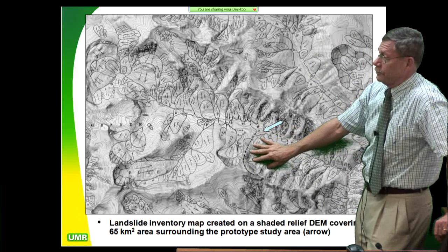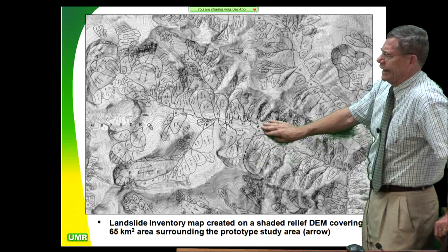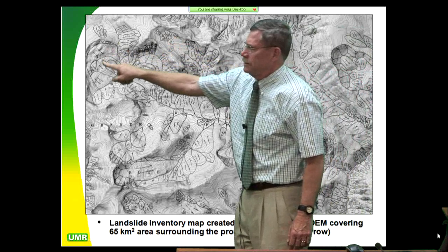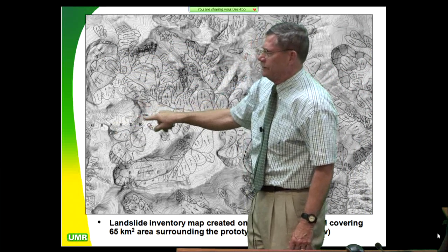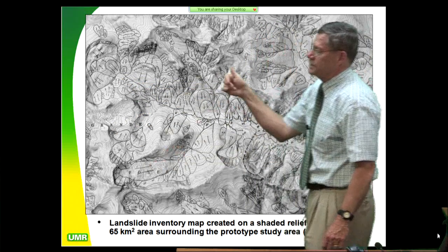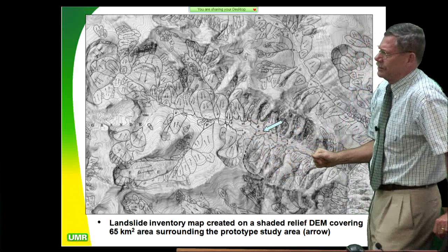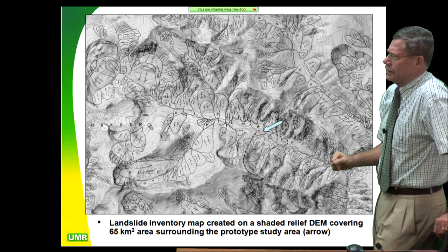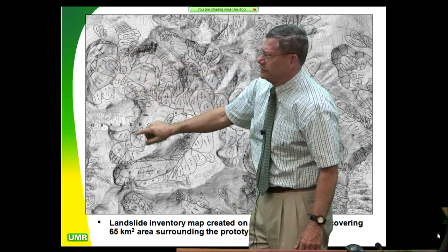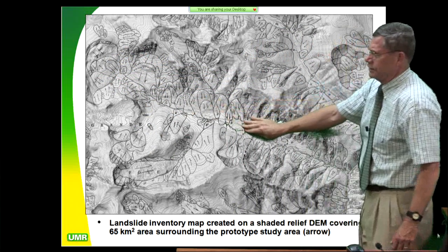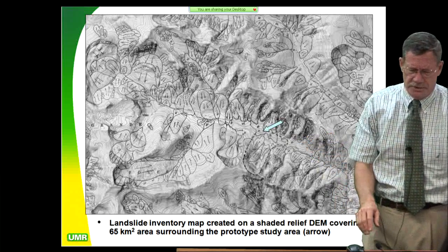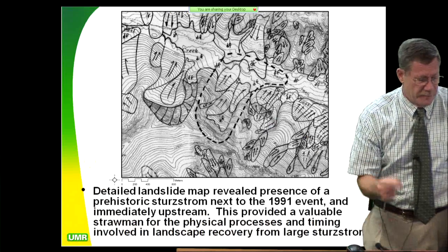This is the topography prior to the failure we were looking at. And there's only about 4.5 square miles of watershed above that point. This is the Continental Divide. And it's a place where the Continental Divide swings 70 miles west of where it is elsewhere in Colorado, the extreme upper watersheds of the Rio Grande River. And so we don't have a lot of available stream power here, and we don't have a long drainage season to remove debris that clogs channels, because we just don't have the watershed area, and we don't have much of a season.